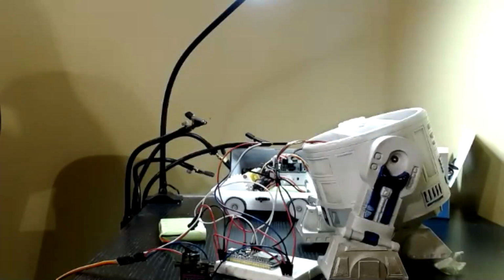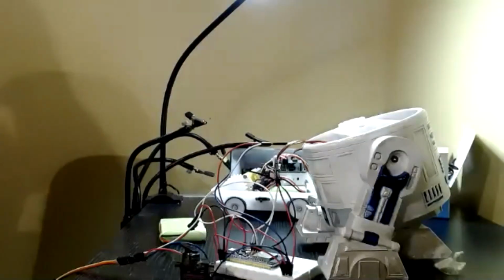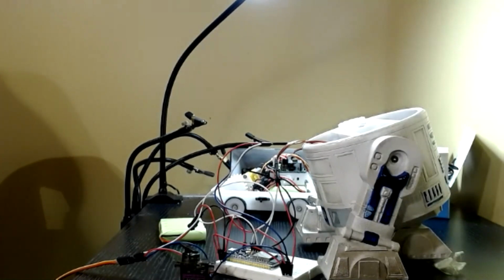I've opened the Blink ESP32 diff steering code and gone to verify it before I've done anything. The only thing I have changed is the authority code for Blink to my particular app. When I verify it, I get an error message with regards to the servo library and compatibility. The reason for that is that I'm using another servo library that I downloaded. I'll put a link in with the code. The default servo library is for Arduino, not for ESP, so I found another one that I used.